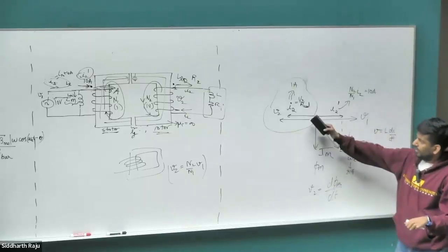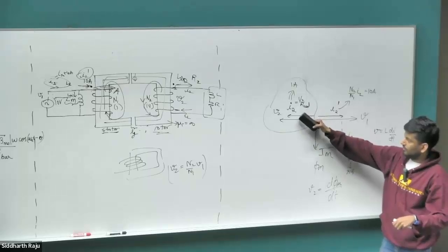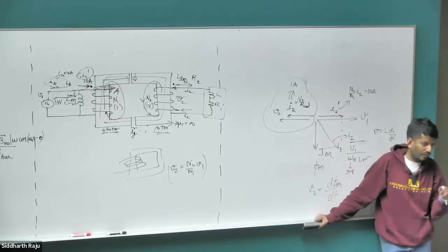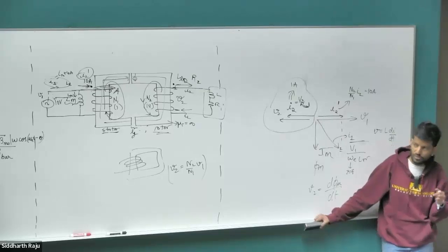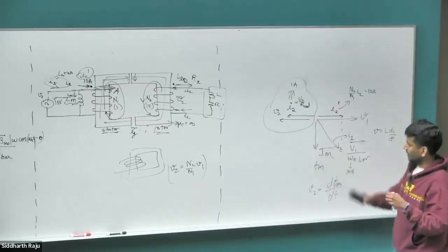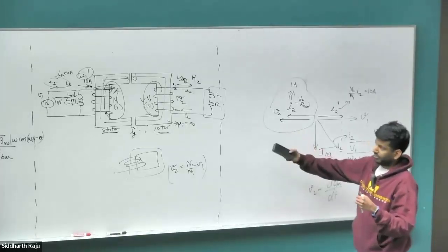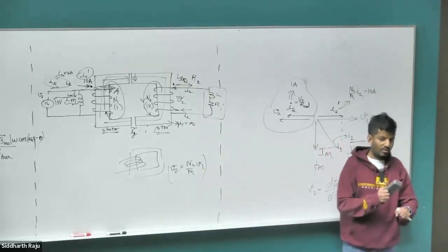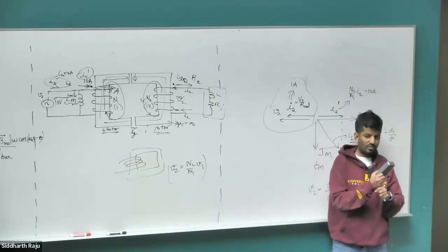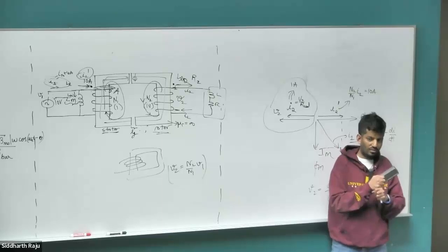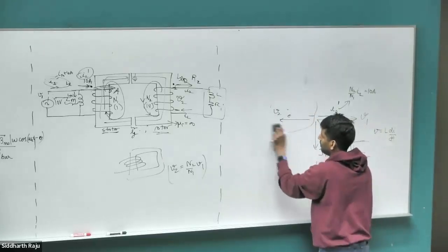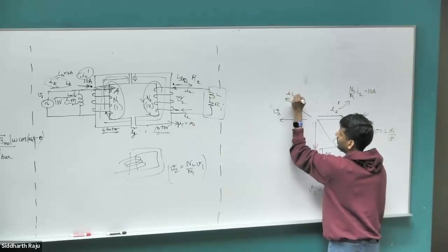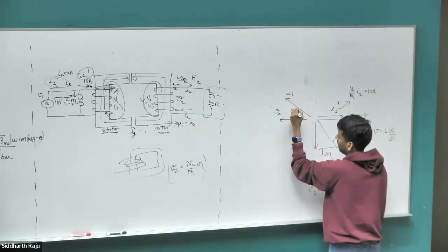Okay, so now let's say I start increasing the inductance on the load side. Is IM going to change? Is IM affected by what's going on at the load? Absolutely not, because it was just the primary voltage divided by its own inductance. That's still going to stay there. The EMF induced on the secondary is also not affected. Just direct relationship. What is going to happen to the current on the secondary side? It will start to lag the voltage. By what factor? An inverse of the impedance of L over R. Okay, so let's call this alpha.